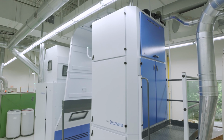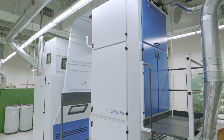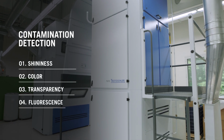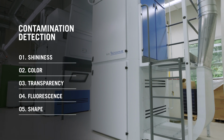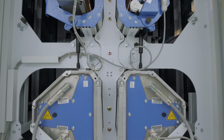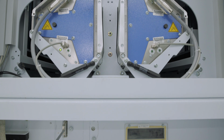State-of-the-art cleaning technology removes unwanted plastic contamination and large organic material from the fiber mass. A series of different cameras detect properties such as shininess, color, transparency, fluorescence, and shape that differ from natural cotton properties. A jet of air ejects the contamination from the moving tufts of cotton, which effectively removes types of contamination not easily removed by other cleaning methods.